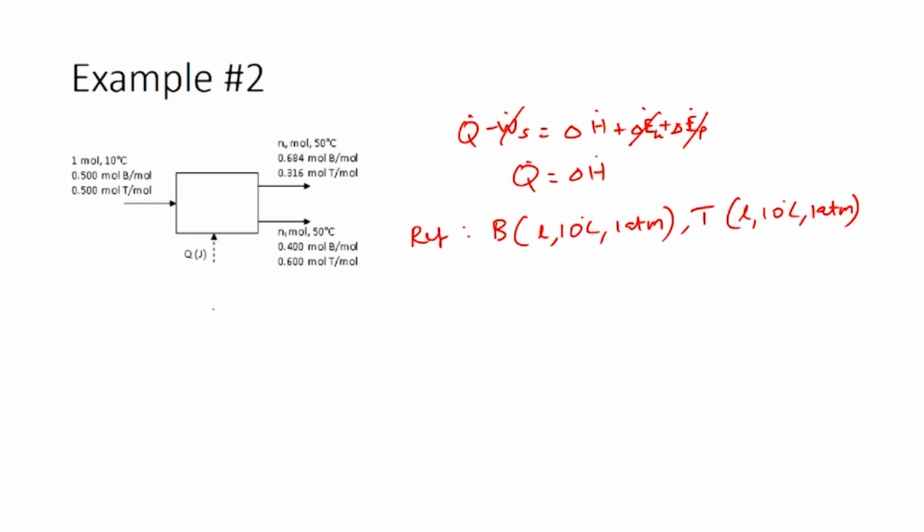So, the enthalpy table would have all the substances which would be benzene liquid, benzene vapor, toluene liquid and toluene vapor. So, here you also have the flow rates which you have to write down, n dot in, enthalpies would be H cap in, n dot out for the outlet flow rates and H cap out for the specific enthalpies of the outlet streams.